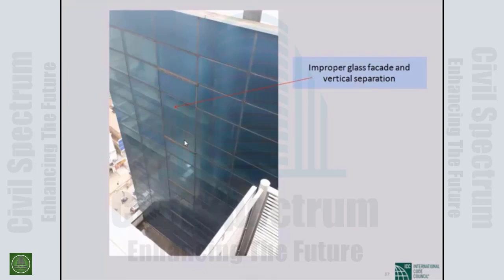You have already seen from the table, which I just finished a few minutes ago, that there is some separation from the first to the second floor, because that table gives you the vertical separation and horizontal separation. But in this case, you see the glass tower, which is very common in Dhaka, particularly in the Banani and Gulshan area. There are a lot of huge high-rise buildings with glass. Almost all of them don't have fire separation. Almost all have zero fire separation. This is very dangerous. That happened in the FR tower with the zero separation. So you have to be very careful.